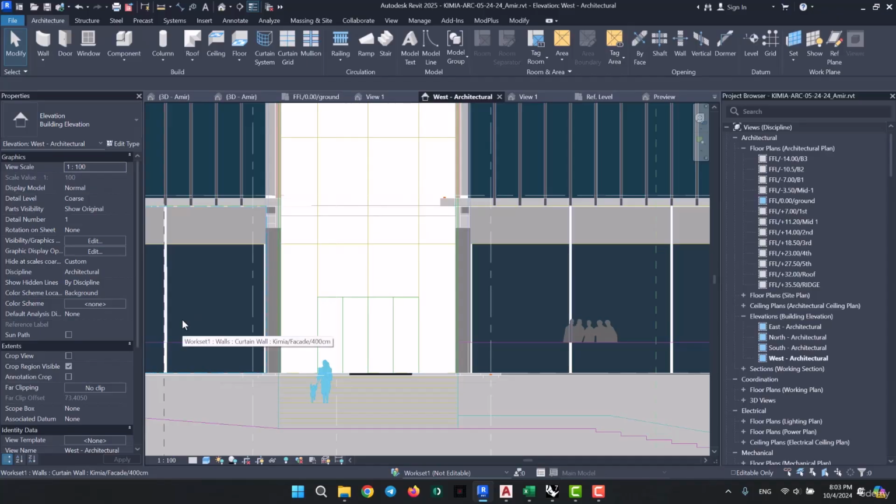Now the thing here is that how are we going to place these slide doors on the curtain walls? As you may already know, we're going to need to replace the panels of the curtain walls with the doors. Therefore, if we want to have slide doors on our curtain walls, then we would need to download a curtain wall specific slide door family. So basically it's just going to be a slide door family that's suitable for placing on curtain walls. Not to mention that it might be a little hard to find, and that it's possible that you might not even find a family with such properties.